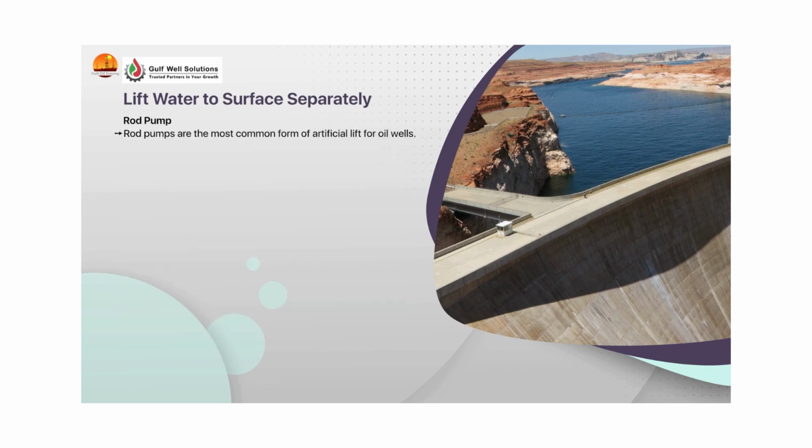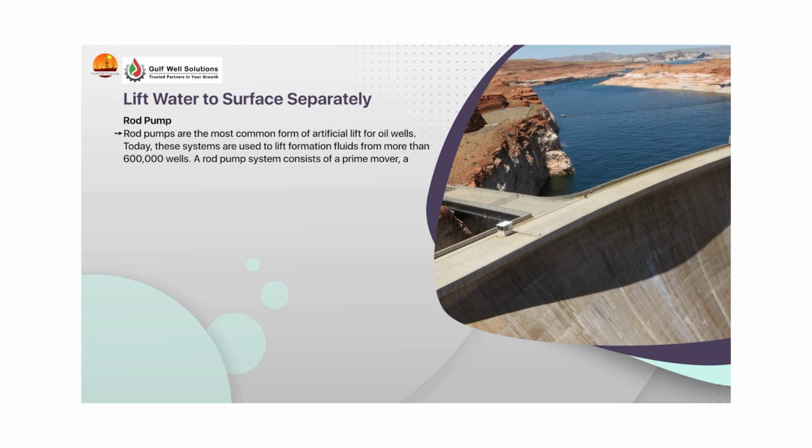Rod pump. Rod pumps are the most common form of artificial lift for oil wells. Today, these systems are used to lift formation fluids from more than 600,000 wells. A rod pump system consists of a prime mover, a surface pump, a sucker rod string, and a downhole pump.